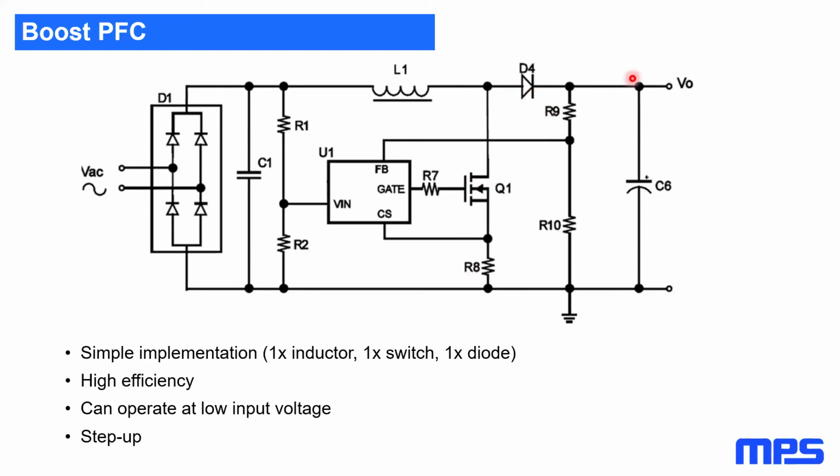And this will create an output voltage which is higher than the peak of the input voltage, because a boost is a step-up solution. It's a rather simple implementation, as you can see, because we only have one switch, one diode, plus this inductor, and of course the control and some feedback to sense the output voltage and regulate it.